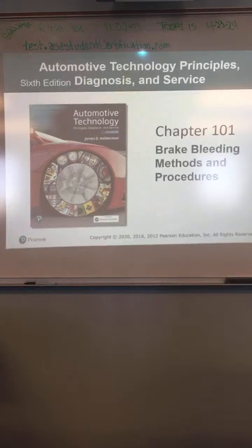There are 3 different methods of bleeding brakes. You can do a gravity bleed, which means you take the top off the master cylinder, open the brake bleeders and just let it drip. It'll eventually get the air out. It takes a long time, but you can do it by yourself. I did that one time on my car when I rebuilt the brake system. I let it sit for 2 or 3 days with the bleeders open, because the whole system was new. Not the most efficient way, but you can do it that way.